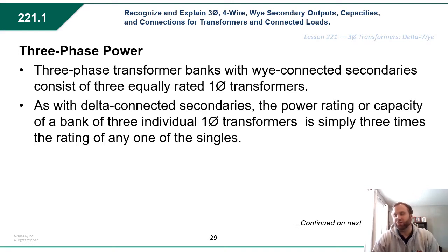The two power transformers, in conjunction with the lighting transformer, take care of all the kVA requirements for the three-phase loads, and then the lighting transformer takes care of all the requirements for the 120 or 240 single-phase loads, depending on what requirements are in the building. So that would be a lighting transformer.